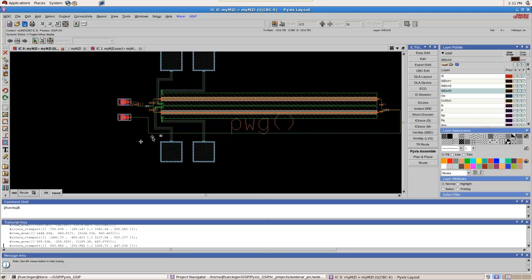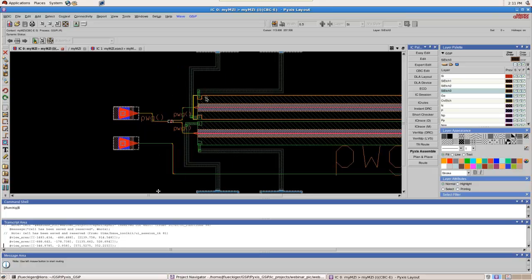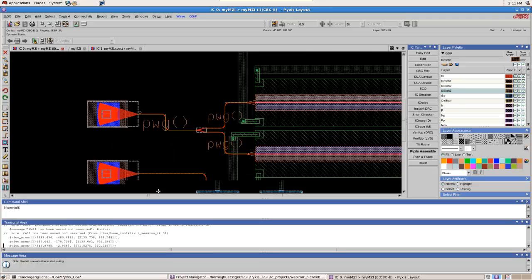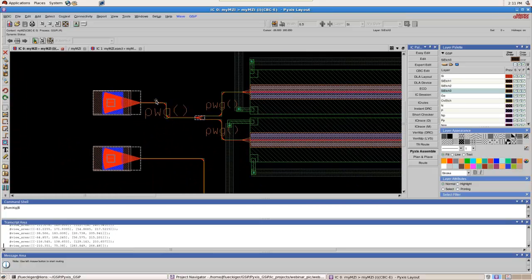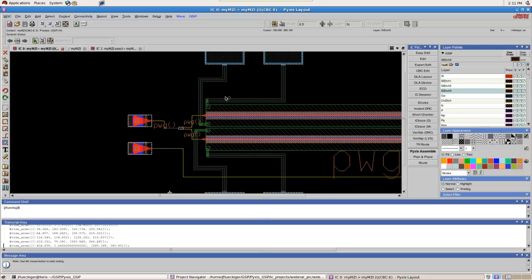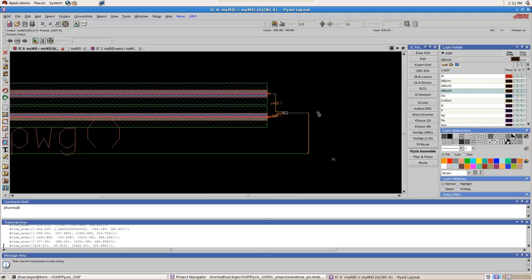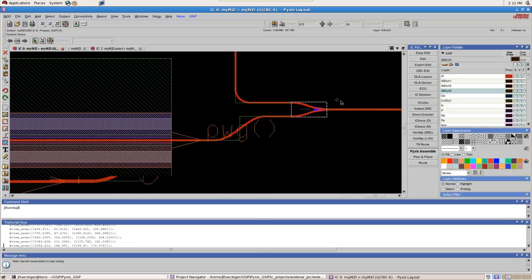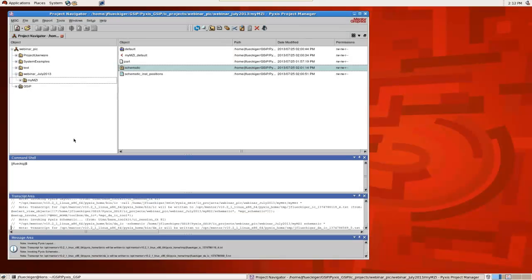Okay, so ideally this circuit could be fabricated. So we could actually put that in our wafer, and after design rule checking, you can go for fabrication. So we have our grating couplers, we have our waveguides, we have the proper bends. We have the mechanical part, so we can actually drive this device. We have our Y branch there. So all the steps are actually done.